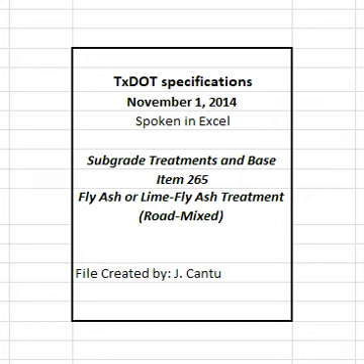Shape existing material in accordance with applicable bid items to conform to typical sections shown on the plans and as directed. When shown on the plans or as directed, proof roll the roadbed in accordance with Item 216, proof rolling, before pulverizing or scarifying existing material. Correct soft spots as directed.